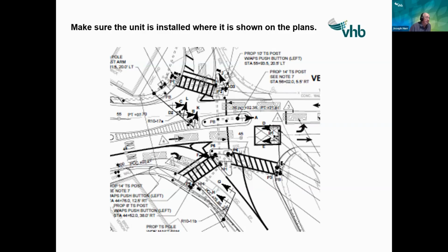It just makes it a lot easier to understand that this ped's associated with P3 and P4, and it's a phase 6 ped. Just mark it out in red and understand if this makes sense and how it's supposed to work before you start going out there and pushing the button and looking at the physical and operational items of the intersection itself.